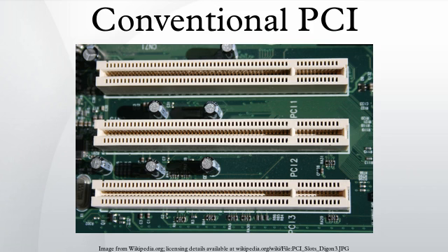Devices connected to the PCI bus appear to a bus master to be connected directly to its own bus and are assigned addresses in the processor's address space. It is a parallel bus, synchronous to a single bus clock. Attached devices can take either the form of an integrated circuit fitted onto the motherboard itself or an expansion card that fits into a slot.